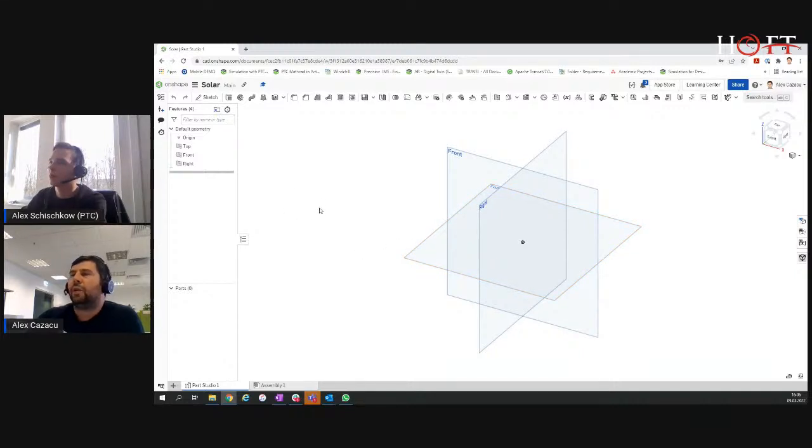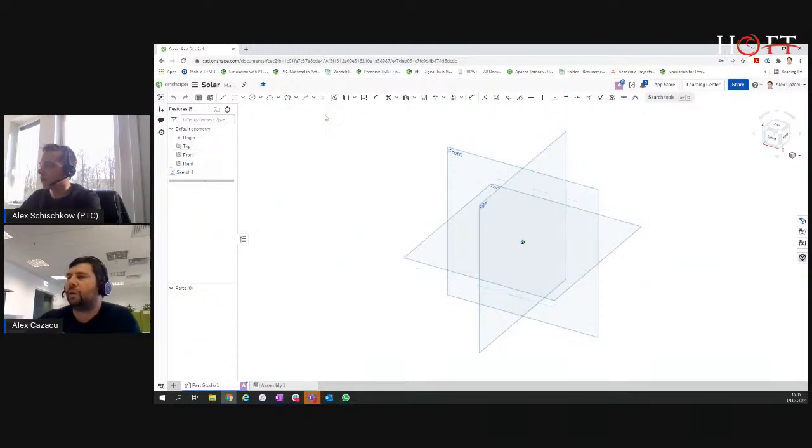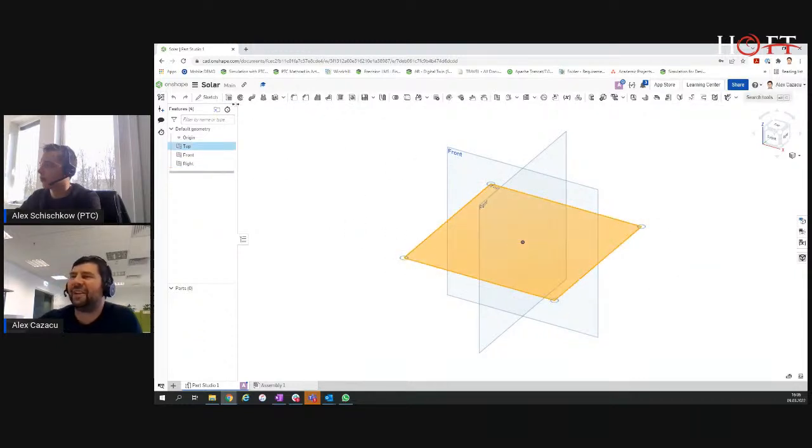Okay, so Onshape is a fully parametric software. It is delivered as a SaaS platform, so again, you don't have to install anything. The platform will work only parametrically. That means that you need to create a sketch and then either extrude it or revolve it, or you can use the sweep. Extrude is when you lift the profile, and I'll just create a very fast profile. Sorry, I'm used to working very fast.